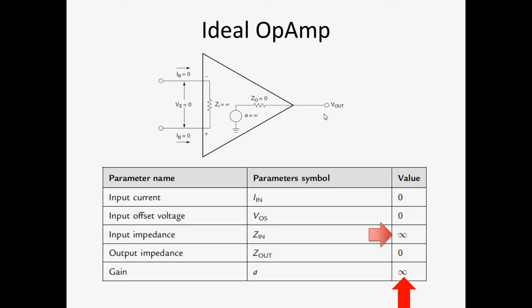A stimulation amplifier is designed to give you milliamperes no matter if the skin impedance is perfect, which is about 5-6 kiloohm, or the skin is not prepared well, so you have like 10-20 kiloohm. However, the thermal effect is going to change. And in the case of an extreme stimulation amplifier, like the cardiac defibrillator, you can actually spark the chest of a person.